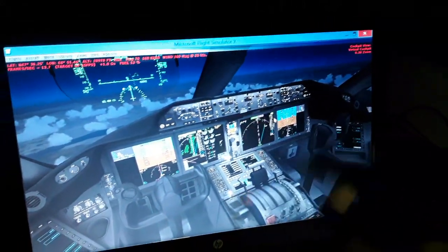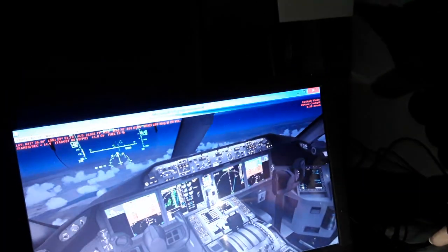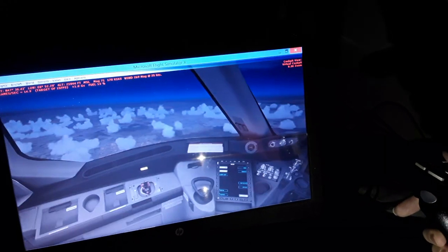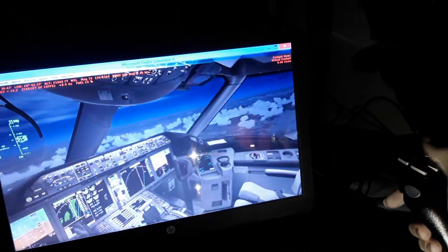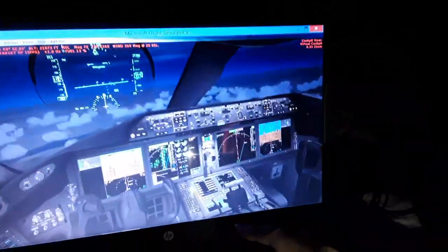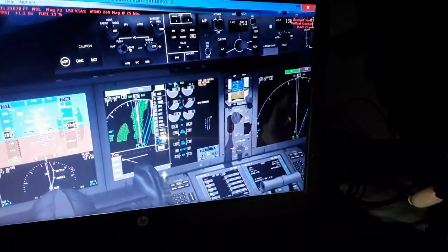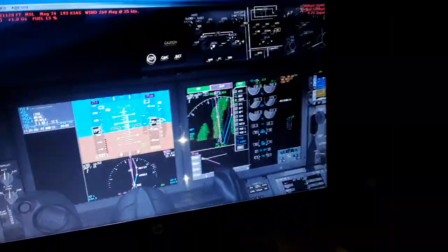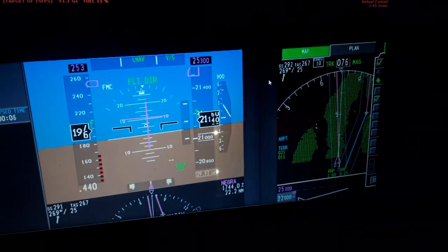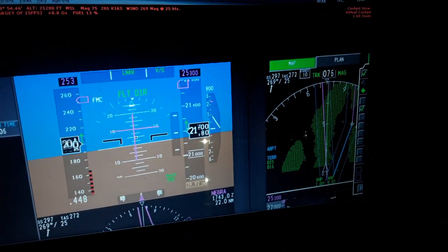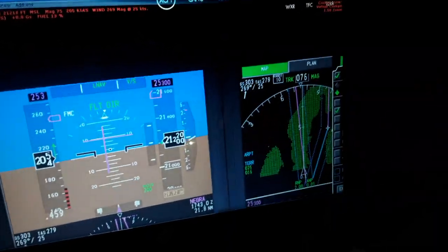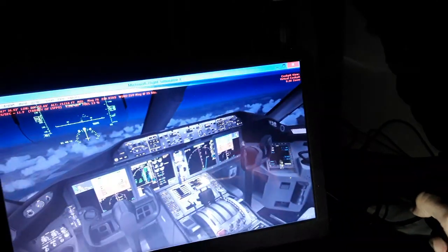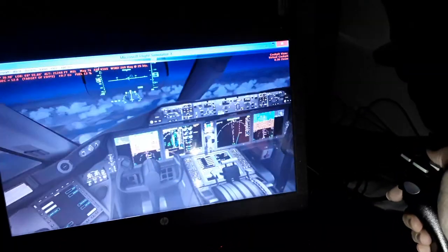So retract all the flaps and give us a higher airspeed rate. So now we are accelerating, and also climb. So this is a very fast acceleration now taking place to avoid also the stall margin.